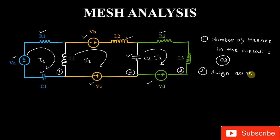all the current to each mesh. Okay, so in that way the first two steps are done. First we identified the number of meshes, and in the second step we understood the direction of the currents, where I have taken the clockwise direction.